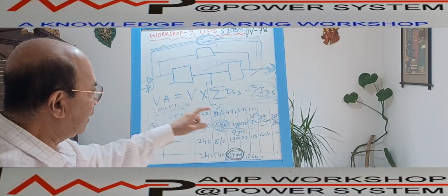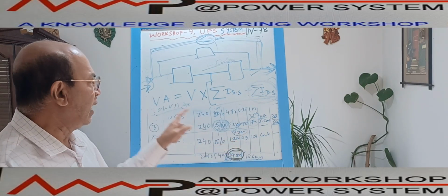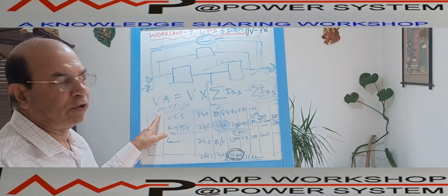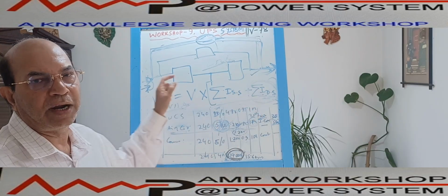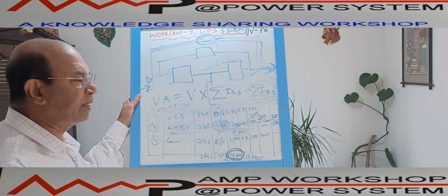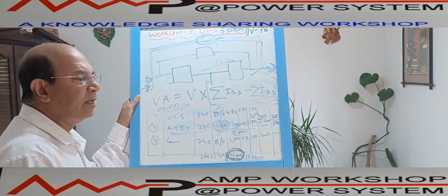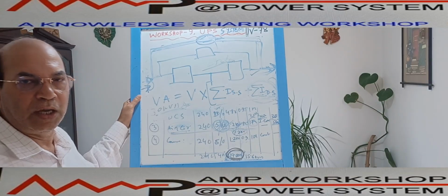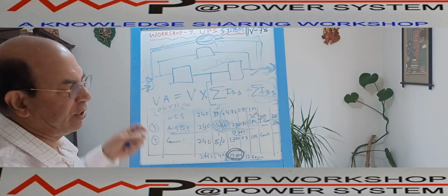But if the time of operation of the dynamic load is more than the short circuit capacity and the UPS cannot cater for that, then I have to include the additional or differential power required for the dynamic or transient current. So this way we have to calculate the dynamic load for UPS sizing. So these are mainly the UPS sizing part.